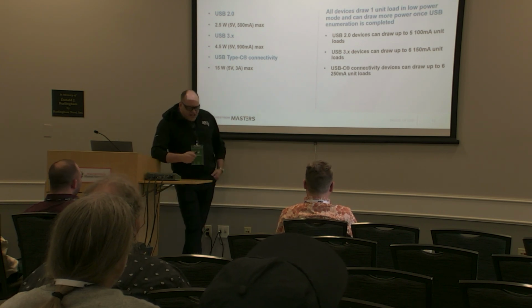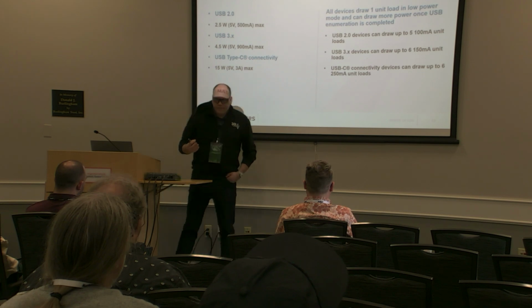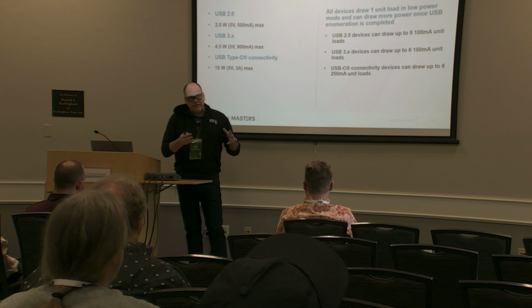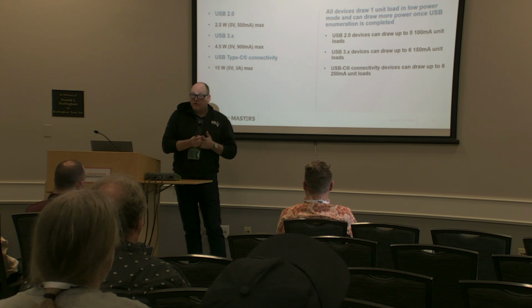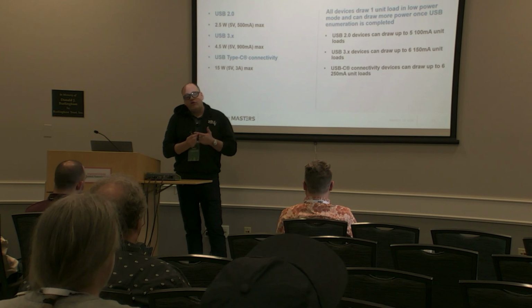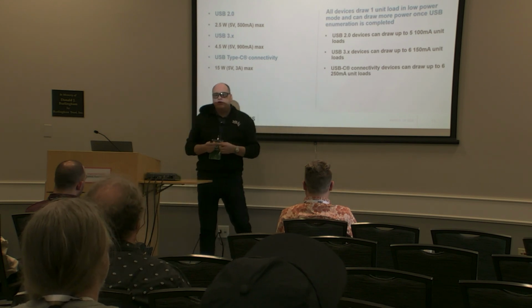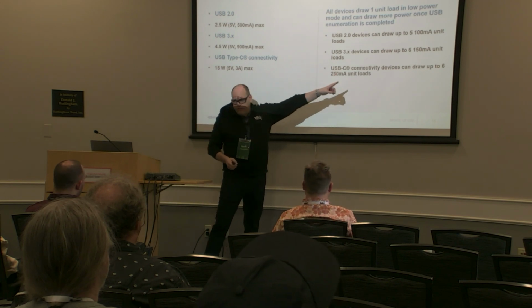I don't have another slide to illustrate this, but I want to dig into it a little bit more and explain. When you plug in a USB device, say it's a webcam, into your laptop, what is actually happening is that it connects on that power pin. There's something connected here, there's a voltage here now. So I'm going to give you 100 milliamps, 1 unit load of power if it's USB 2, 150 milliamps if it's USB 3.